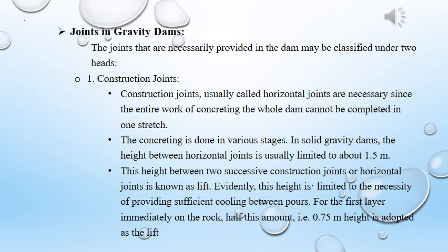Joints in concrete dam. To reduce the thermal stress and subsequent cracking in the body of the dam, most concrete dams are provided with joints. These joints may be grouped in two categories. The first is the construction joint and the other is the contraction joint.